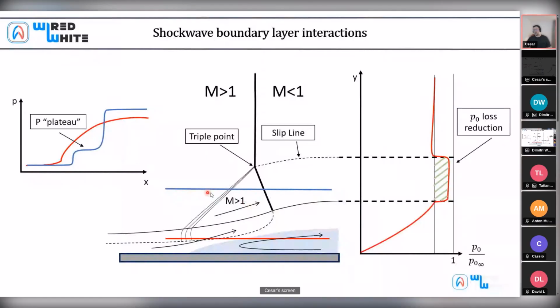But here, thanks to the fact that we have crossed an oblique shock before the normal shock, the total pressure is not so abruptly dropped, right? As a consequence, we have a gain in the total pressure after the shock system, right? This is what supersonic intakes try to do before bringing the air towards the engine, which needs to be subsonic. They decelerate the flow through several oblique shocks in order to give the optimal conditions to the engine.